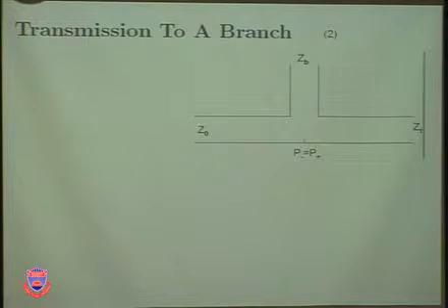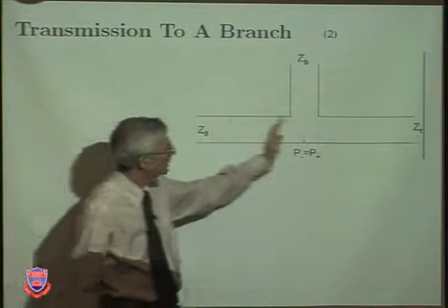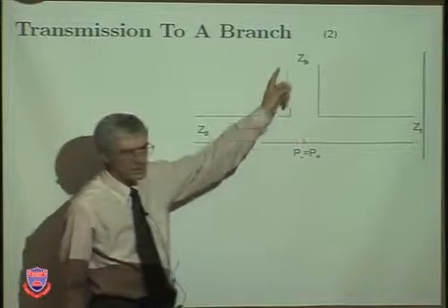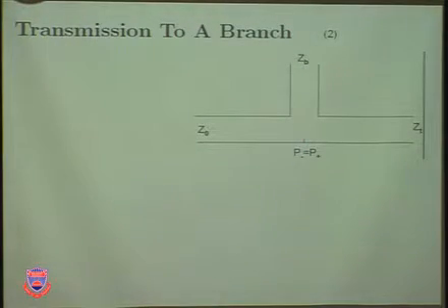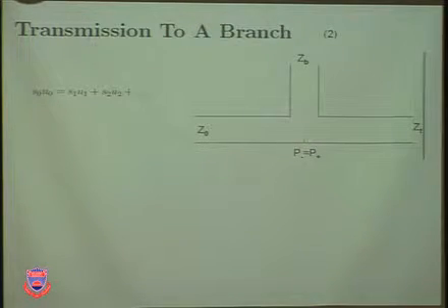But when you have a branch like this, and these are very common, and you have sound pressure propagating, but then there's another duct that takes off. It's not dissimilar to the previous one, but basically we have a relationship between the areas and the particle velocity to all different branches, but the pressures must be the same.